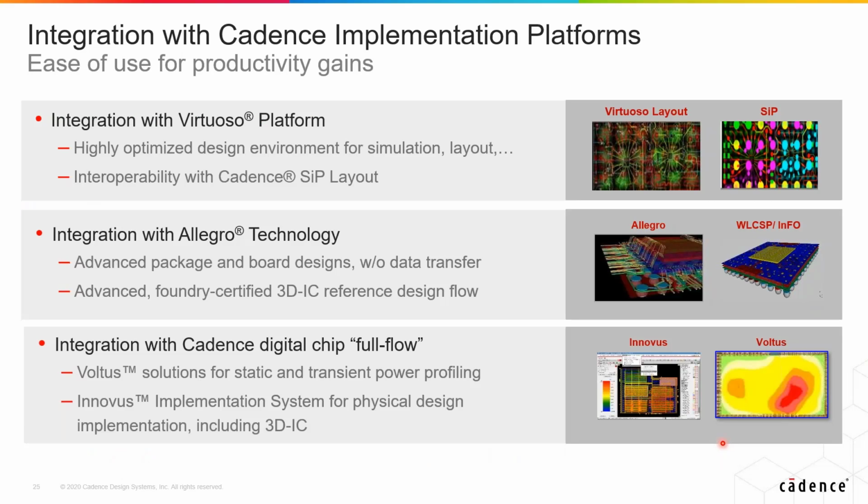A few words about integrations. Currently, we have an ongoing project to integrate Celsius Thermal Solver with the Virtuoso platform, SiP layout technology, and also Allegro technologies. We have a close integration with Voltus at this moment to get chip power into the equation. Then together with Celsius Thermal Solver's chip, package, board and enclosure capability, we can solve system level thermal problems.